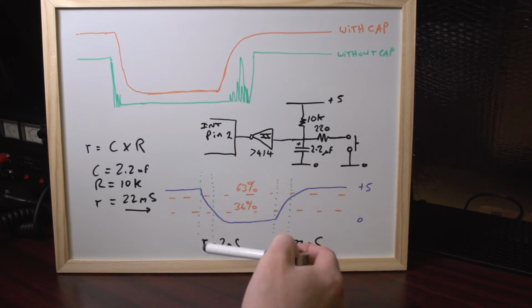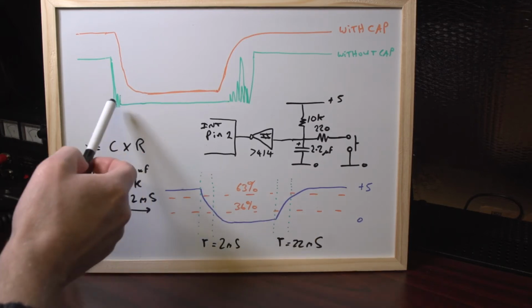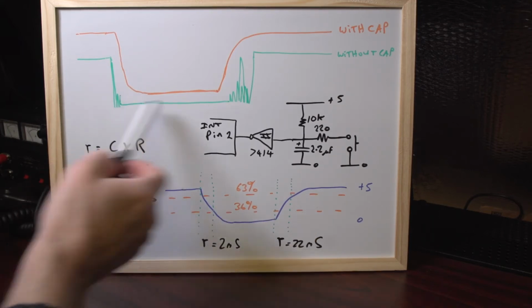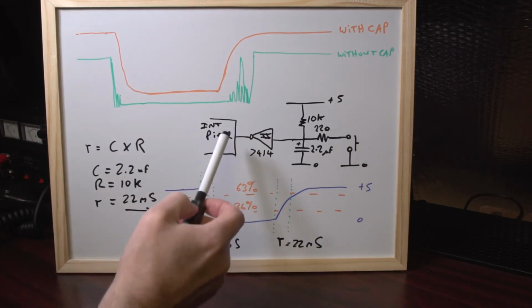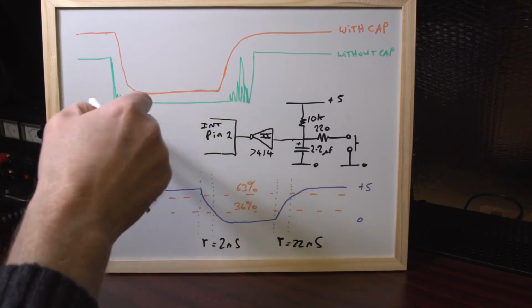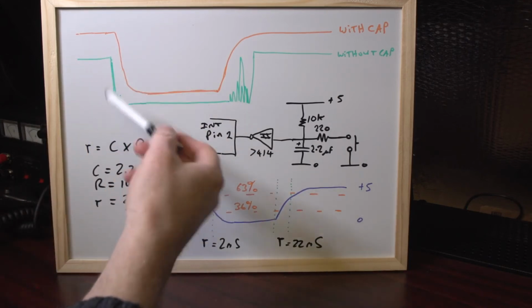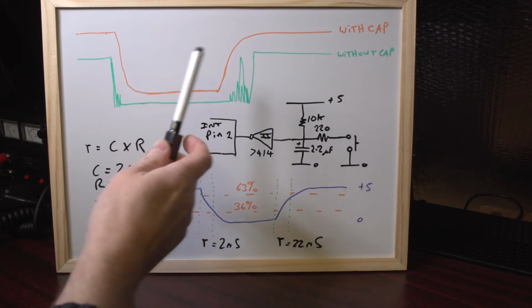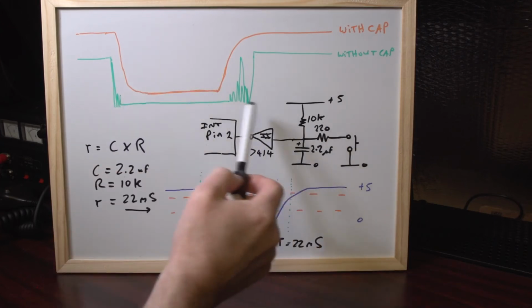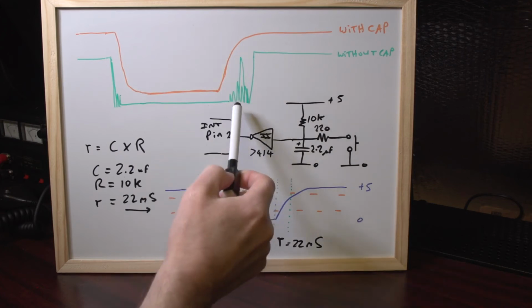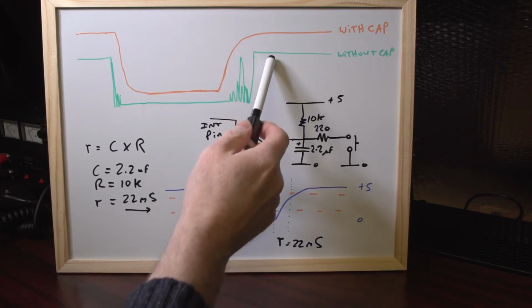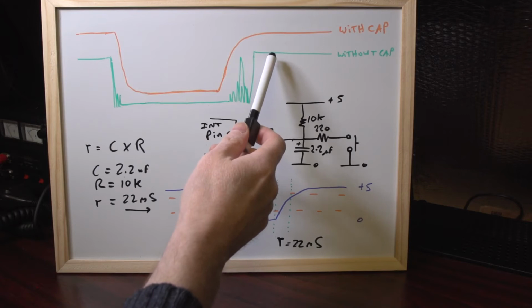You get a brief amount of on-off signals. Those on-off signals, the contact bounce that we get from the switch, are enough to trigger the input of an interrupt pin and cause problems, because instead of 1 pulse, now we're getting 2, 3, 4, 5 pulses, whatever it happens to be. The same happens when we release the button. We get even worse, a lot of contact bounce at the very end before it eventually settles and the contacts settle at a high state.